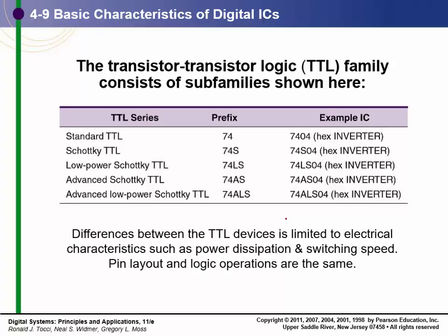However, I've worked on circuits and I'm very familiar with systems that work beautifully when you have 74XX parts in them. 74XX parts became obsolete because that was the old school. Faster, lower power parts came out, so they quit making the 74XX. Someone dropped in a 74S replacement. The circuit quit working. It would not work. And the reason was that the part was too fast and some of the glitches would cause problems.